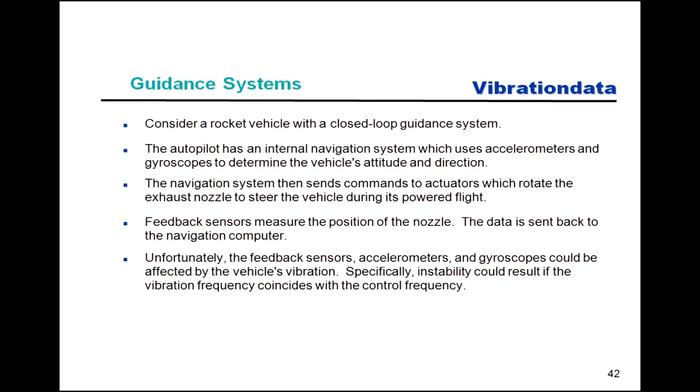So sometimes people think, well, I've got a hard drive. I need to mount it on a vehicle that's undergoing vibration, and I'm going to mount it via isolators. Well, that might not be such a good idea because that low isolation frequency you're going to set up could interfere with the control algorithm. Because the guidance and control engineers, well, I'm calling them GNC engineers as if they were aerospace engineers, but you get the point.